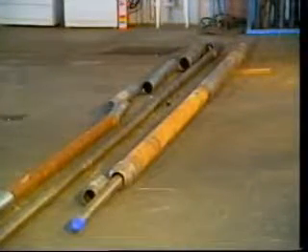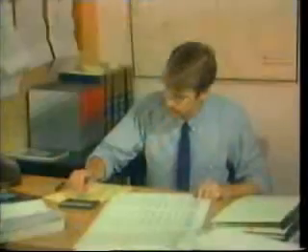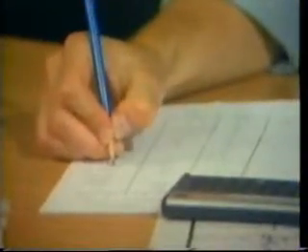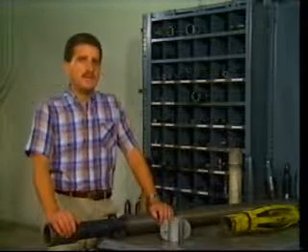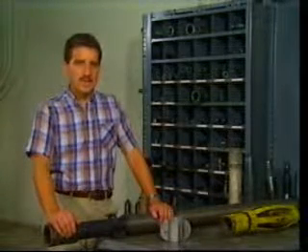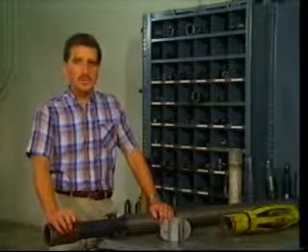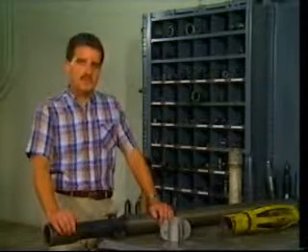4. The use of proper tools and procedures. And 5. The application of current techniques and design methods. The cased hole gravel pack is the most common method of mechanical sand control employed during initial completions for light to medium producing oil and gas wells.